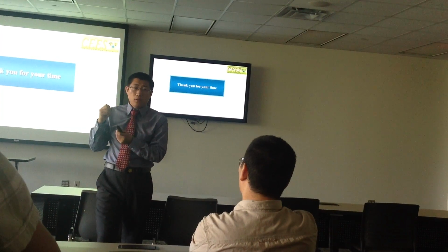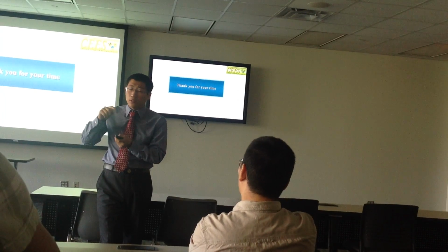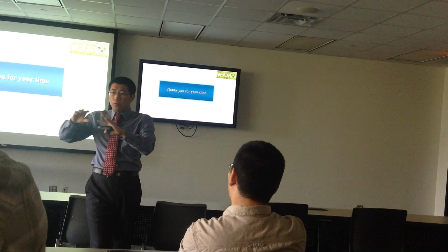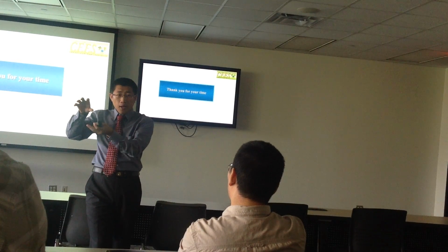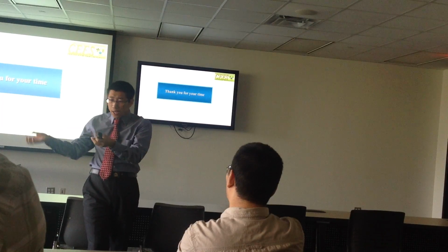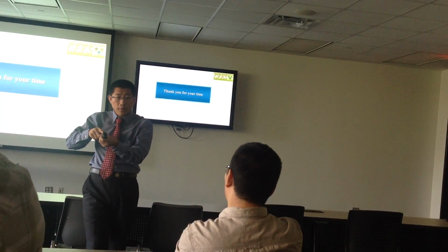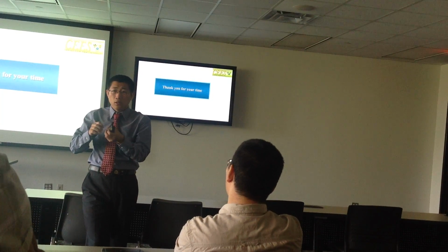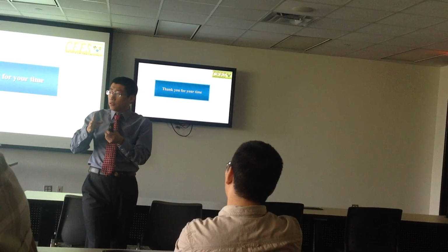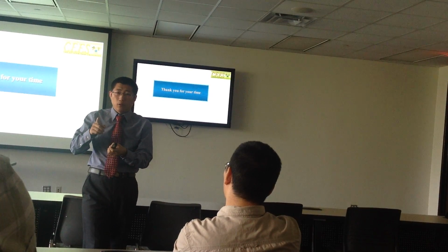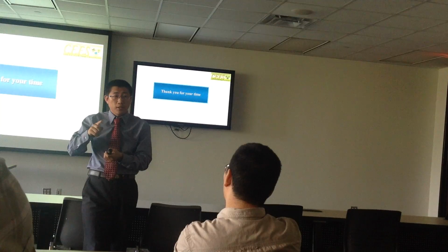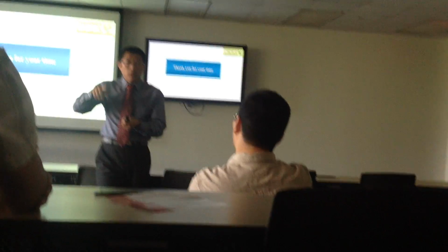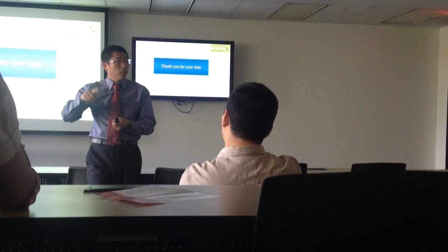As I mentioned, in the process we calculate the Y plus value. First we make different meshes on the boundary layer, then we do the simulation and get the result, then come back to calculate our Y plus value. When we calculate the Y plus value, we can't get exactly, for example, 30, sometimes we get 29. That's also acceptable, and this is the common way researchers work.